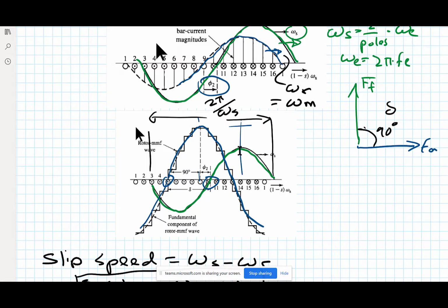And you can't really always say it's a field or an armature, but the stator is close to a field, and the rotor is close to an armature in the way they behave. But if you look at the zero crossing point differences, there is a 90-degree difference, which is most of that angle difference, plus this little phi here.